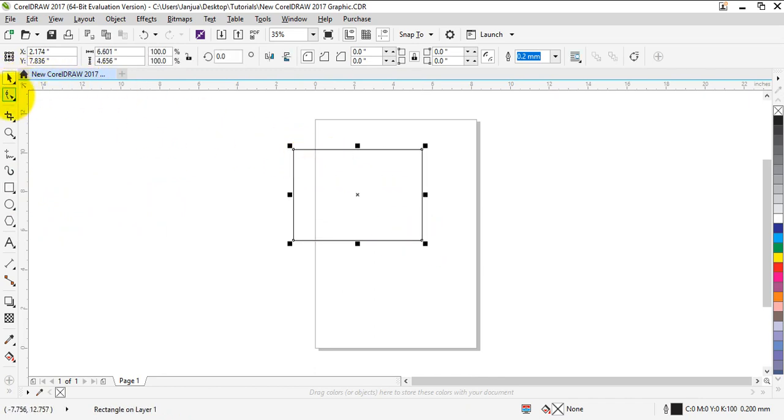So if I select this and pinch it right here, the edges of the box will turn into curves. The more I drag this, the more prominent the curves are. If you want to change the shape of the box, first press Ctrl Z to undo and go back to how it was before, with edges.